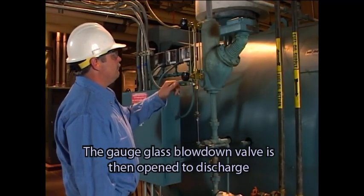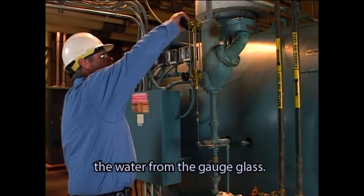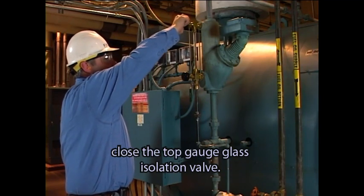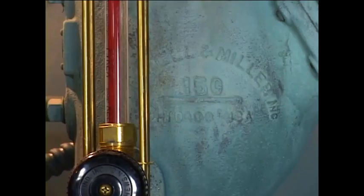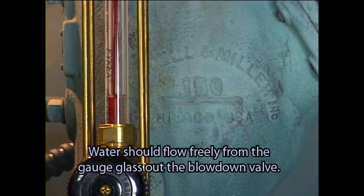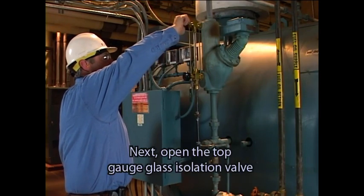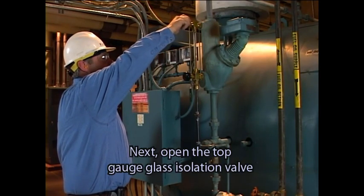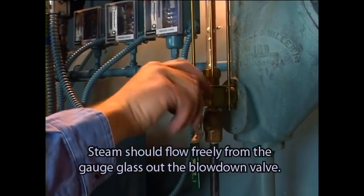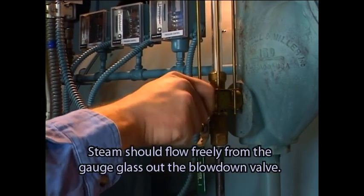The gauge glass blowdown valve is then opened to discharge the water from the gauge glass. With the gauge glass blowdown valve open, close the top gauge glass isolation valve. Water should flow freely from the gauge glass out the blowdown valve. Next, open the top gauge glass isolation valve and close the bottom gauge glass isolation valve. Steam should flow freely from the gauge glass out the blowdown valve.